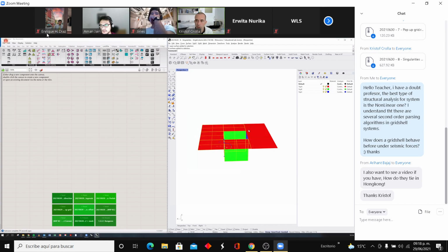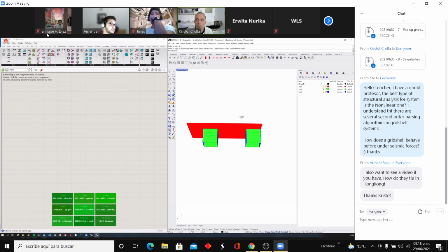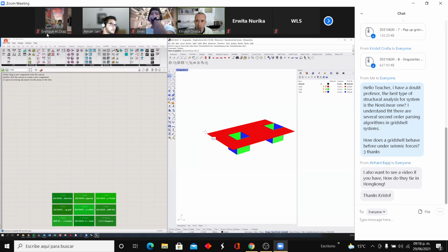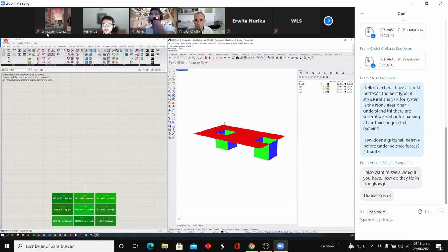And then if you want to, you can continue and expand it very easily just by copying exactly these planes. Like this one, you'd have a double column setup if you'd want to. And then, of course, you can also later on always add lines to deform this or to pull things to the foundation or add anchors. This is the equivalent of a neutral shape that can then be deformed. So this becomes really a design tool now, but the design actions that you need to take are actually quite restricted.